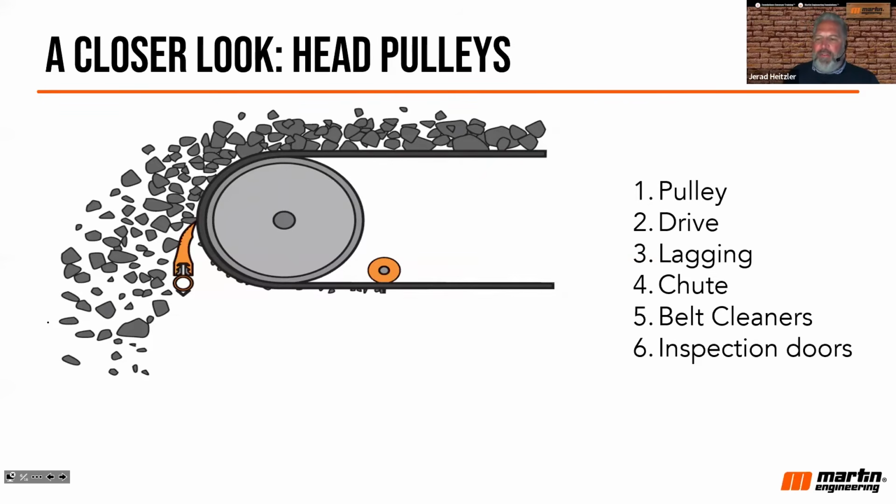Just real quick here on belt scrapers, and I'm not going to get too in depth into this. Earlier, I mentioned secondary cleaners and tertiary cleaners. Typically, tertiary cleaners and secondary cleaners are on the return path further down in this area here, which we call the secondary zone. Most conveyors are going to have at least a primary cleaner. In many instances, a primary cleaner will not eliminate all the carryback that needs to be eliminated. Therefore, secondary and tertiary cleaners can be added.